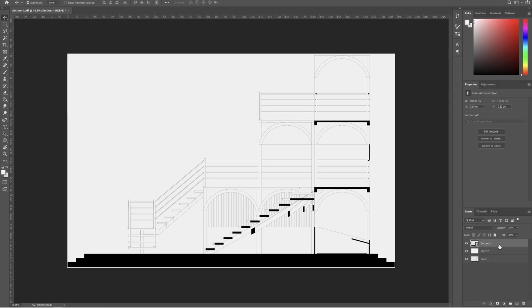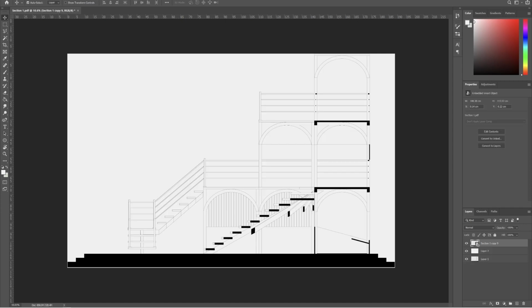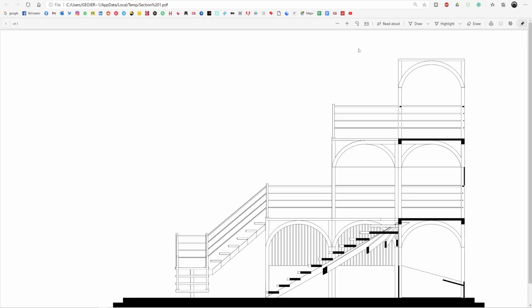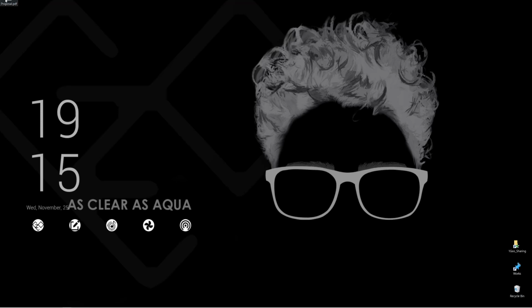As you see, the line weight got lighter. You can make a bunch of copies to make it darker. But still, it's not a reliable solution. Let's keep this non-destructive. Now, this is a smart object. When you double click on it, it opens in your PDF viewer. Here's the trick. We're going to change your default PDF viewer to Adobe Illustrator.